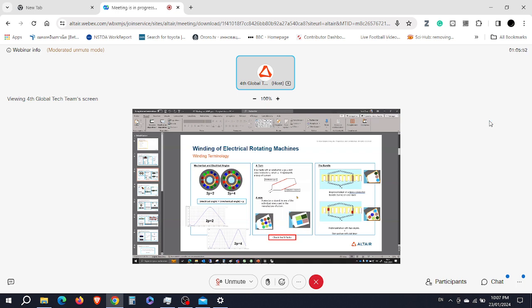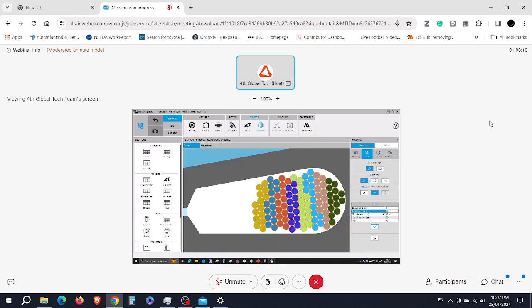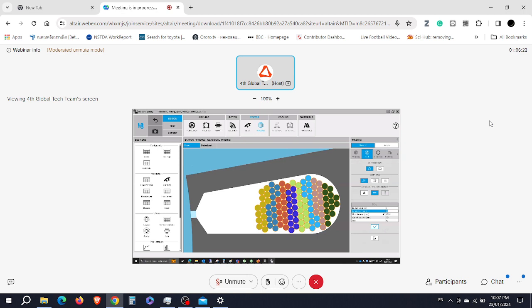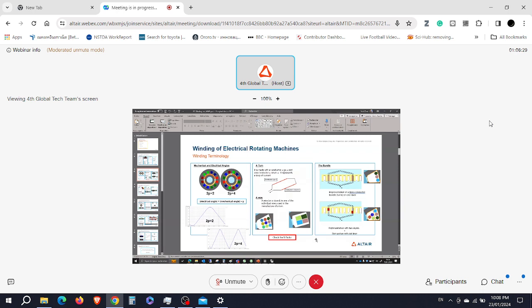Remember, N dphi by dt, the N is really the number of turns. And for the number of wires in hand, we actually use multiple wires per turn in order to reduce the skin effect. Otherwise, if we use one big wire with a big diameter, I will use copper for nothing because there will be a skin effect. So using wires in hand allows us to reduce the impact of this skin effect and use copper in an efficient way.